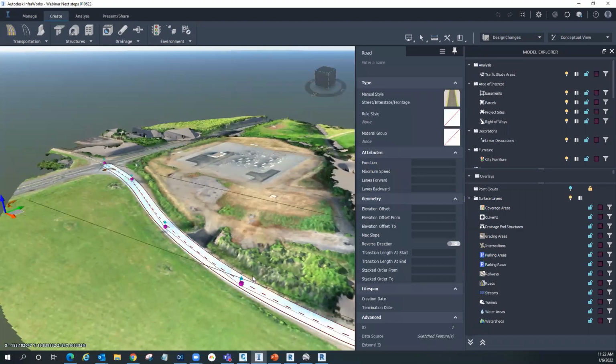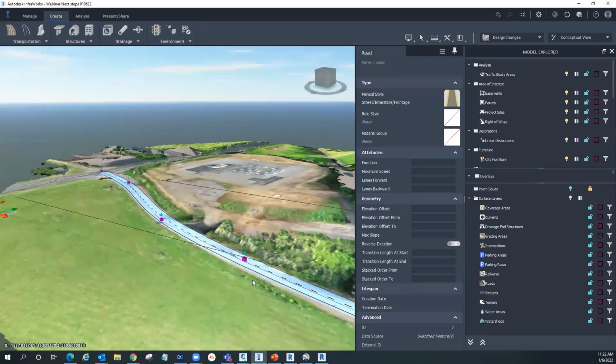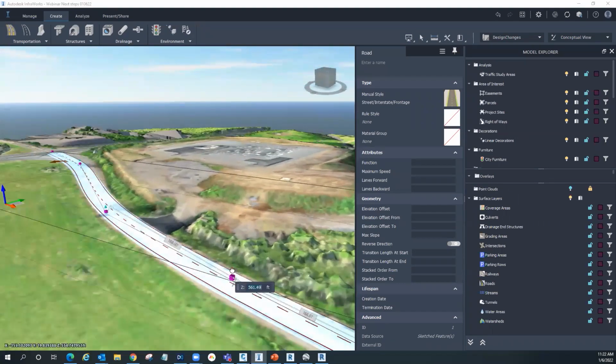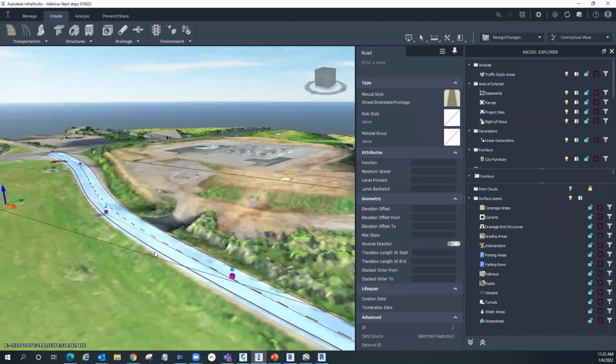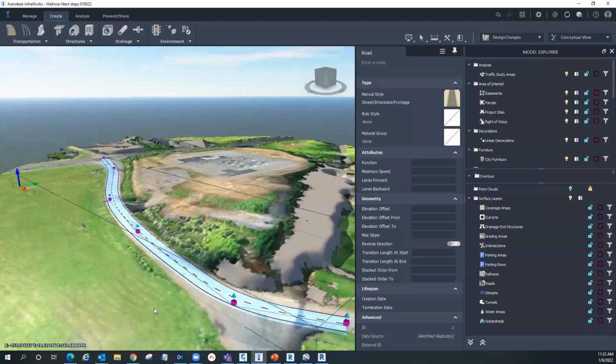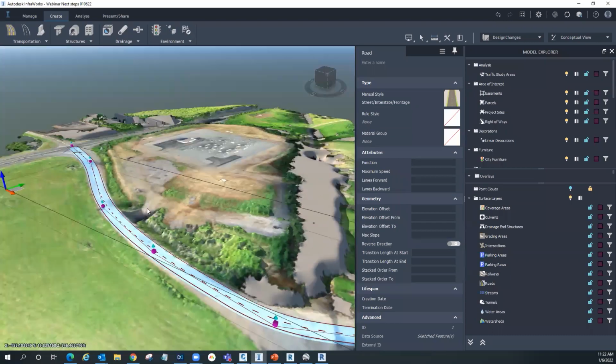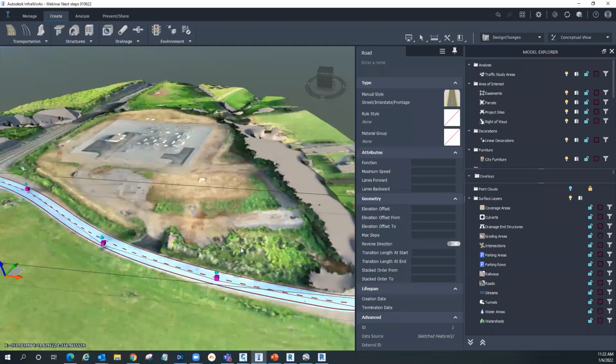All right, so maybe this road's too low here, so we're going to bump this up, and Infraworks is going to put in the grading objects for us. We can change and update a lot of this information later on, but I'm in planning road right now, so let's raise that up so that we see something different when it comes back into Civil 3D.